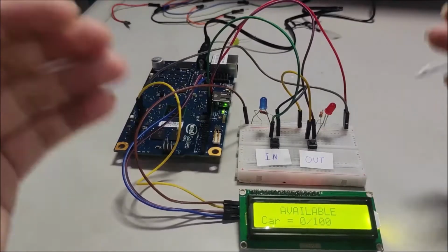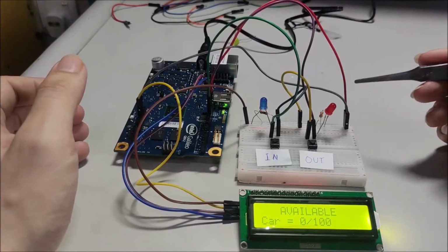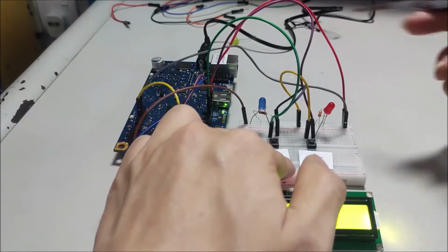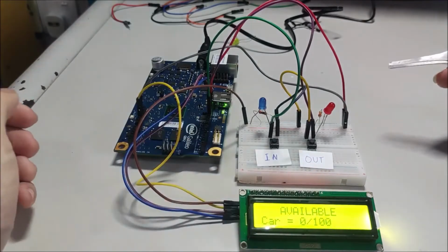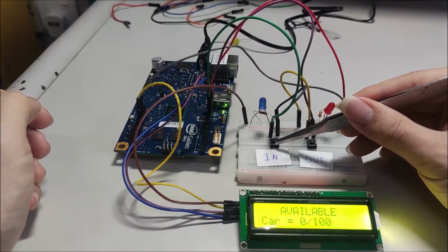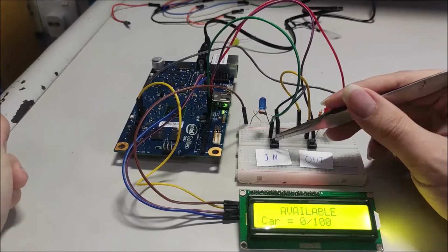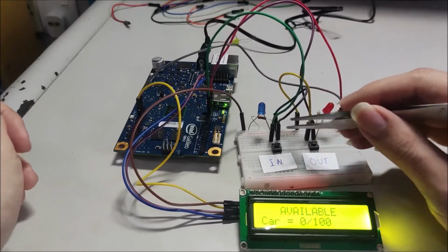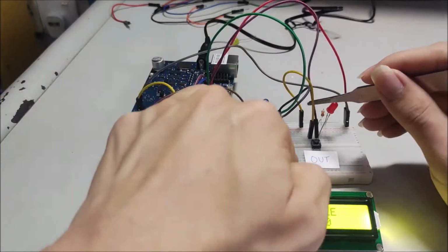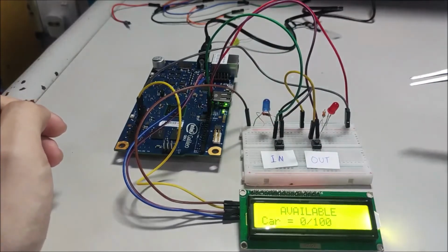Right, so first of all, this is how our circuit looks like. We have connected the VCC 3.3 volt into this row, so the whole row will be 3.3 volt, and then we connect to ground as well for this row. These two buttons are the sensors: this is the entry sensor, and this is the exit sensor. The entry sensor is connected with pin 12, and the exit sensor is connected with pin 13. These two pins are input pins.